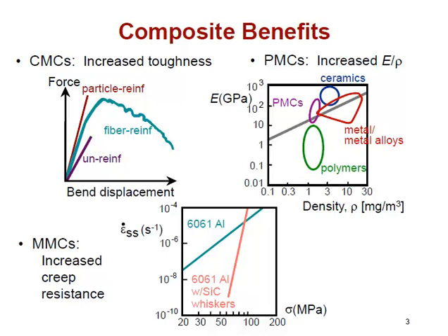We can get somewhere around 2-3 orders of magnitude increase in modulus with less than an order of magnitude increase in density, with the highest being with addition of a metal reinforcer there in the red, and a big range on that. Metal matrix composites, we're looking at addition down on the bottom center, looking at the effect of the addition of a silicon carbide whisker.